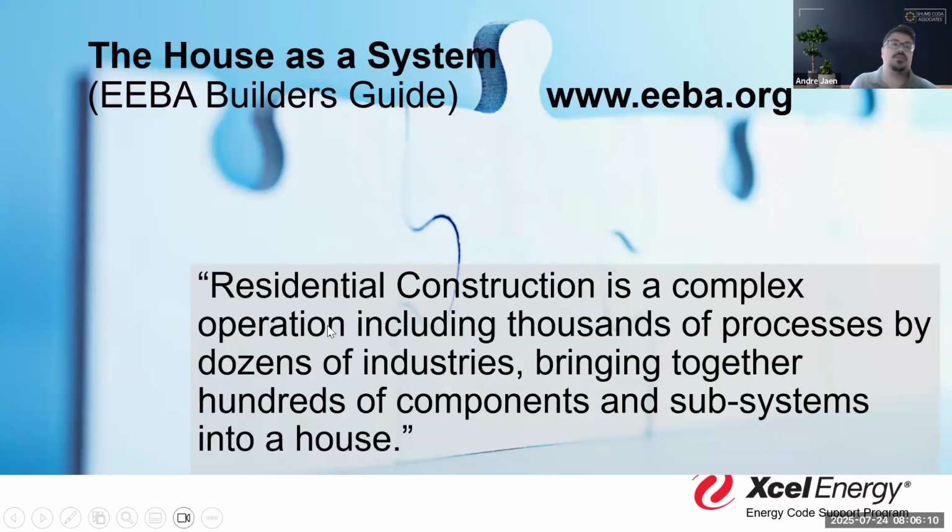So this is a nice quote that I really like when we talk about this and really start getting our head around, okay, we're thinking about the wall holistically today, and we're going to be thinking about these three components in it and how they work, which is that residential construction is a complex operation, including thousands of processes, dozens of industries, bringing together hundreds of components and subsystems into a house. And there's no better example in my mind than looking through all your barrier systems because you have penetrations through all of these components, but only one is going to serve as the air barrier, which means that's the one that you have to seal to.